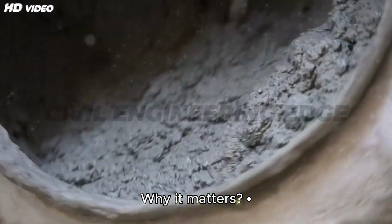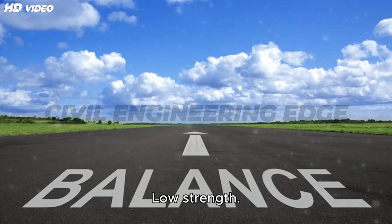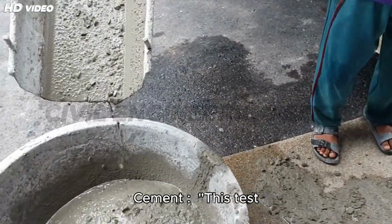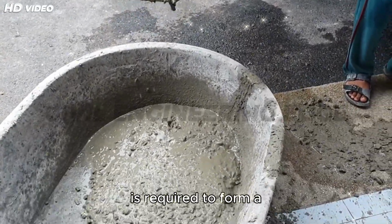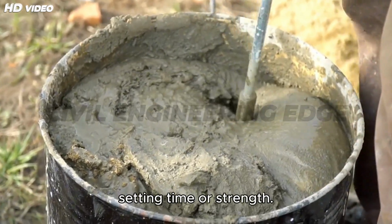Why it matters: very fine cement increases water demand. Too coarse, low strength. Fineness ensures balance between strength and workability. Standard consistency of cement. This test determines how much water is required to form a cement paste of standard consistency, which is essential before testing setting time or strength.